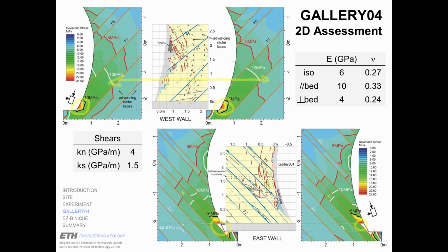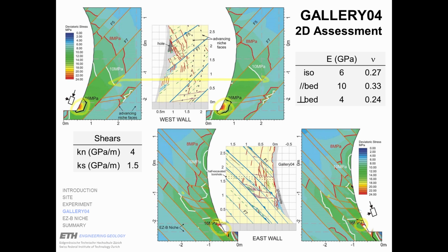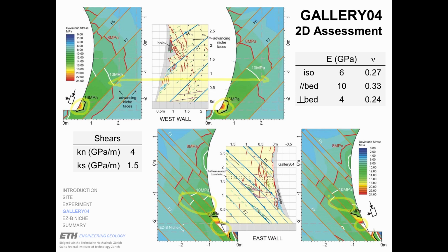Now, if we include bedding parallel shears, we have a strong change of the calculated deviatoric stresses because most of these bedding parallel shears have been reactivated in shear in response to the excavation of Gallery 04. When we add on top of the bedding parallel shears the south-southwest oriented shears, we again see strong modifications of the initial stress field.